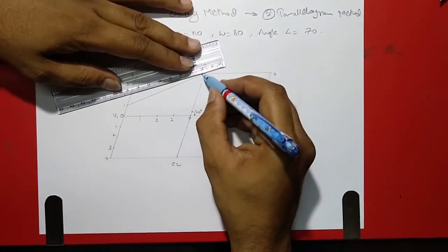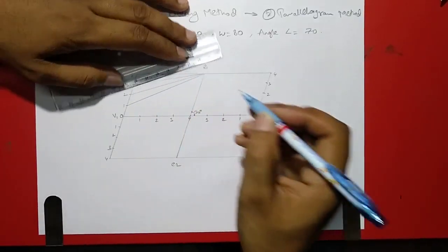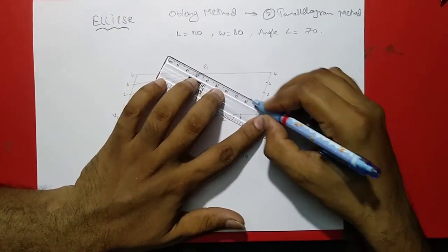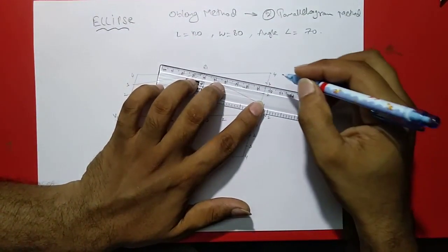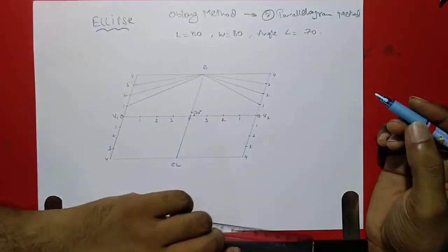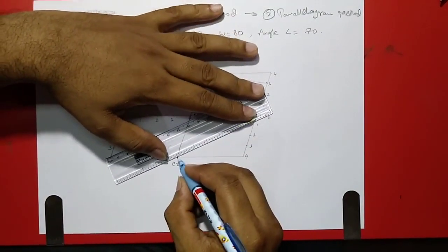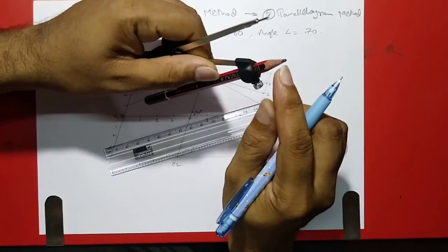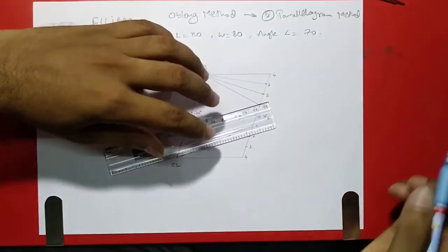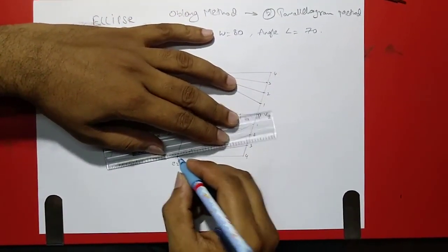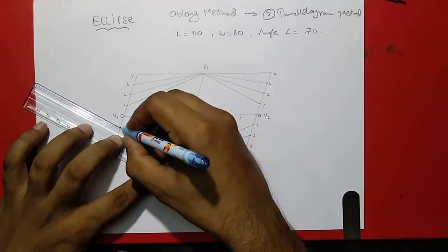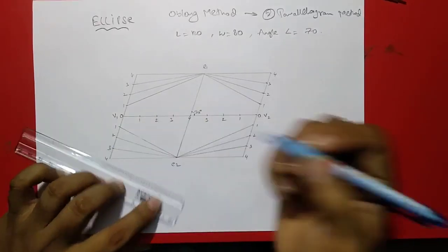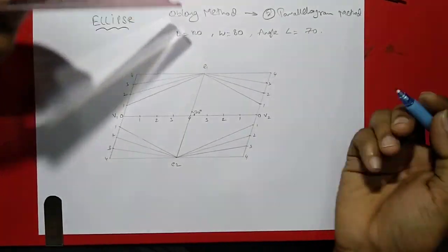Here you can see I'm drawing all the lines very light. Only the curve should be dark, and the tangent, normal and points we have mentioned here. I'm using a 0.7 mm HB mechanical pencil for this, so I'll get uniform thickness of the line because the lead coming out has a uniform cross section, rather than any pencil that would get blunt with gradual use and again we would have to sharpen. So for this purpose I'm using this 0.7 mechanical pencil, HB. If I apply a little more pressure I can draw dark lines, or if I apply very light pressure, I can draw light and thin lines.